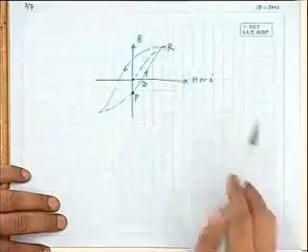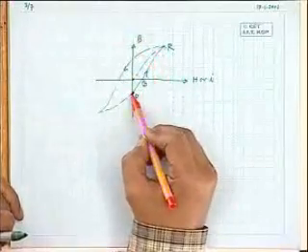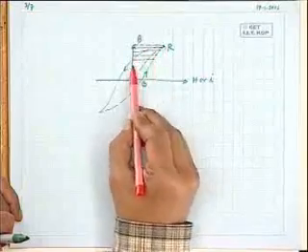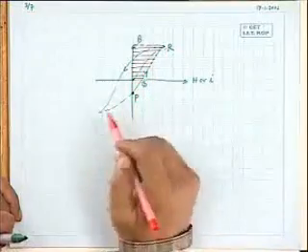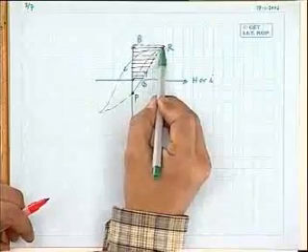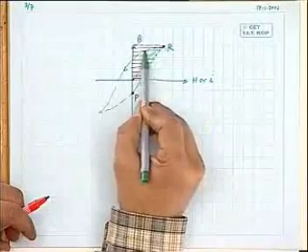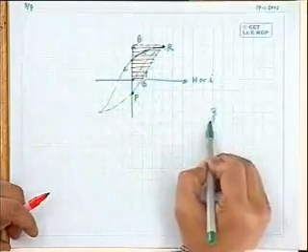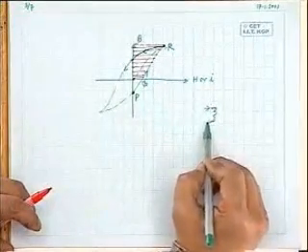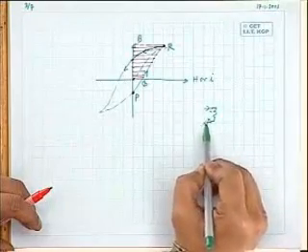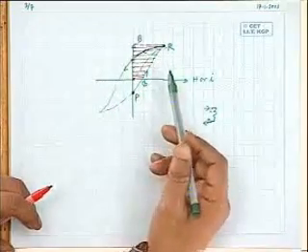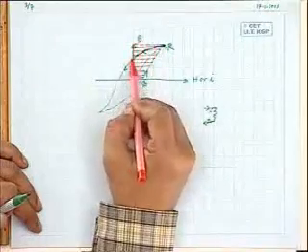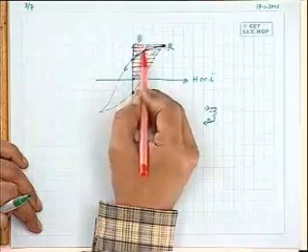Energy will be received because I is positive, dB dt is positive. So which area will give you the amount of energy received? When the current changes from 0 to I max, it will be this area, H dB, this area. Then after it reaches I max or H max, current decreases, and so long as current is positive in this zone, the current direction in the coil is still positive because H is positive, but dB dt has become negative. So the energy will be fed back to the supply, and that is this area, which I double hatch.